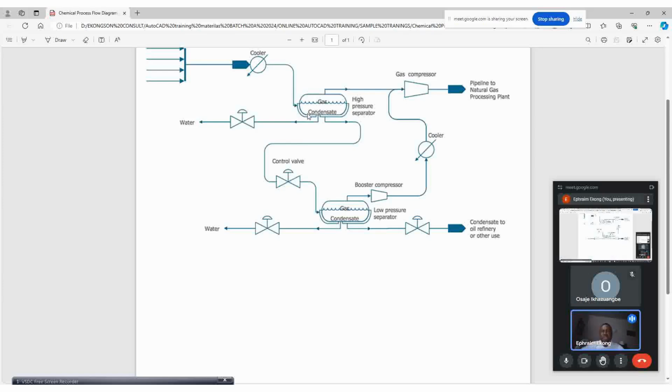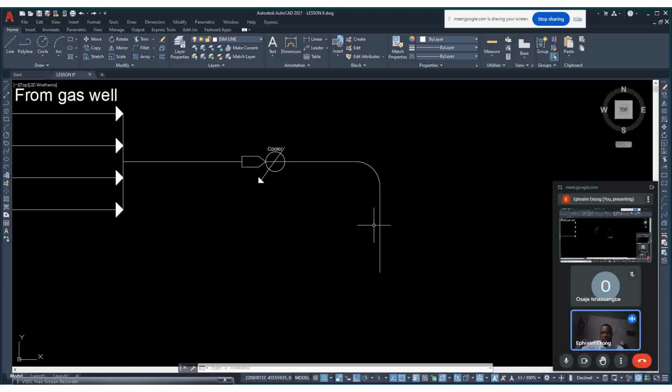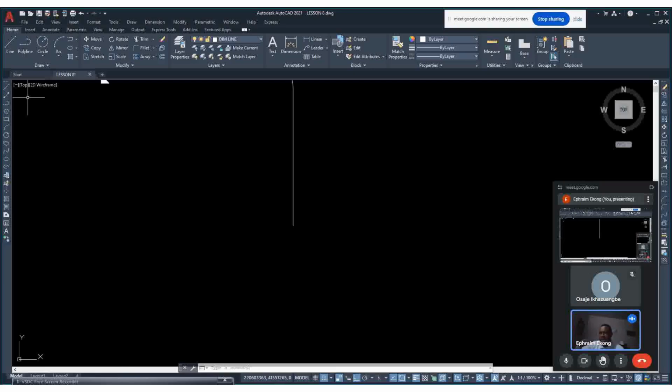So after that, let's achieve this one. We could say from here to here should be 35, 35 the distance. Okay, so let's just do it. You just pick a line here, click here, and take it this way. Type 3500. Press your enter key.